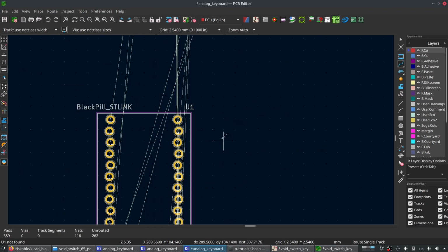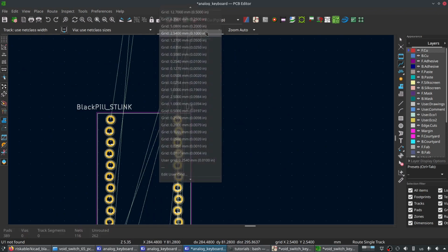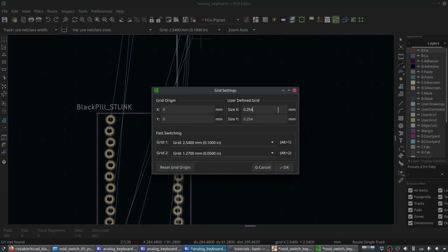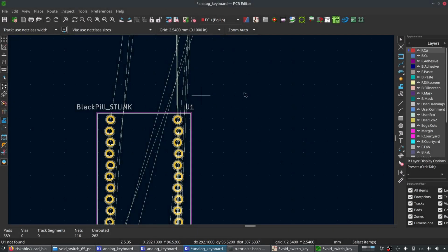That's all that means. So now that we set up our net classes, let's fix the user grid, which I'm looking at right now, and I'm going, oh, that's not right. So normal keyboard spacing, the space between keys, is precisely 19.05 millimeters, right? But we don't want that because some keys are 0.25 of that. So the simplest way is to just type 19.05 divided by 4. Or if you want a little bit finer control, you can go with 8. I usually go with 4, 19.05 divided by 4. And there we go. So that's now our user grid.